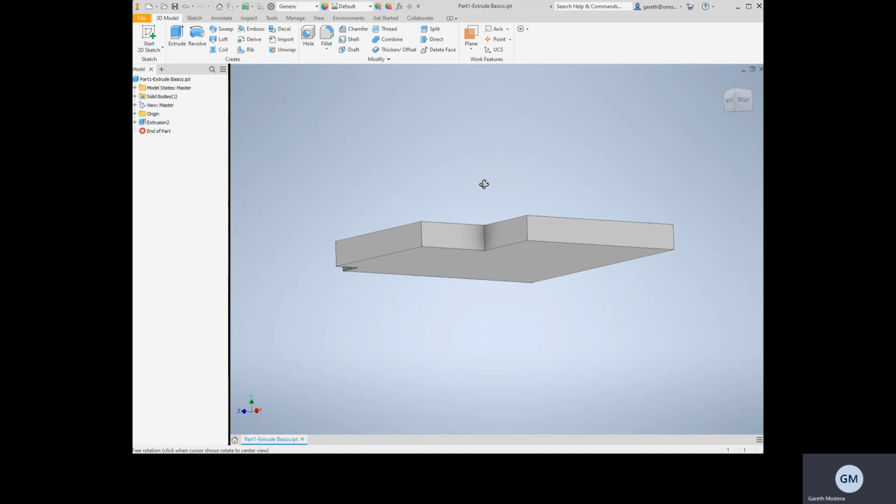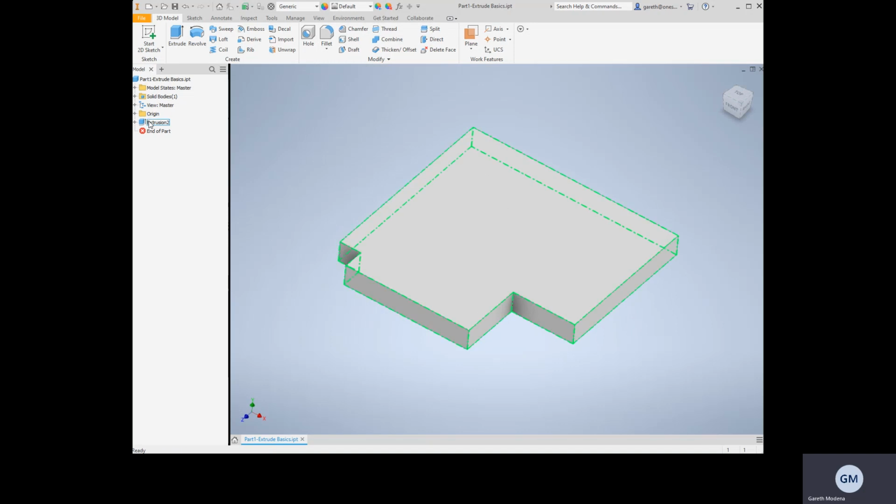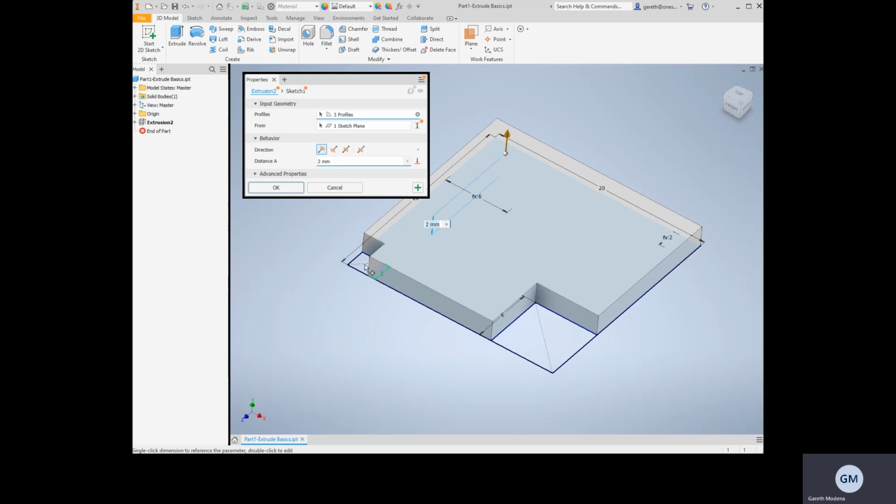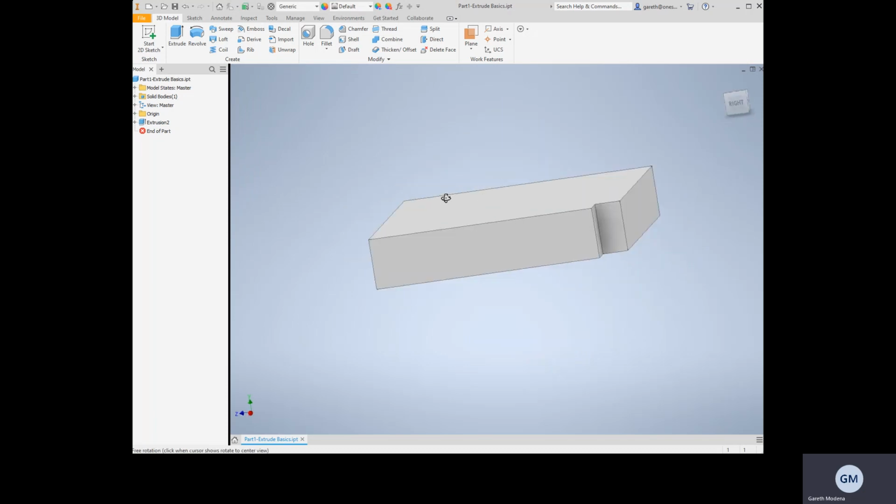So it generates an extrude and adds it to the browser history. If we want to modify the extrude feature that's been created, I recommend double clicking on the icon. In some cases, if you don't click fast enough, it wants to rename the feature. In this case, I just get into the force of habit, double click, specify either additional profiles. In this case, I'm going to add a profile, then deselect other profiles. You can switch your sizes and then select OK, and it'll do an update.